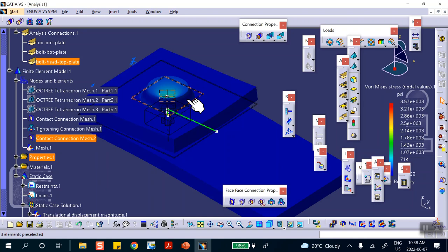So in reality, you have to create a contact between the shank and the top hole, the shank and the bottom hole, and say, don't penetrate. Right now, I don't know, because these are almost zero clearance there. As soon as it deforms, it goes sideways, one way or other. It penetrates it. So the level of modeling will tell you how reliable these things are going to be.